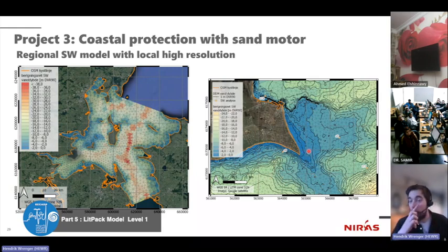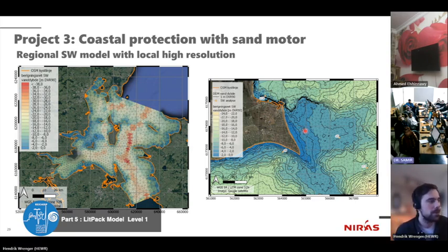And that's exactly now the one point of discussion, where the spectral wave model and the wave transformation that is available in the hydrodynamic modeling of the LitPack have both their strengths and their weaknesses. The spectral wave model has some formulations for breaking, etc., but it's all on a source term basis.